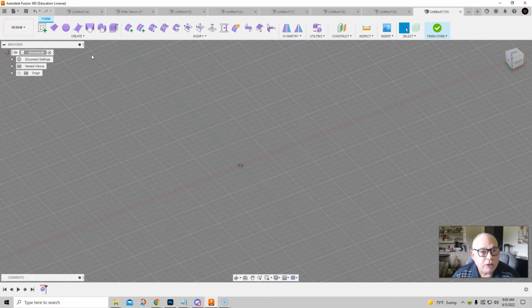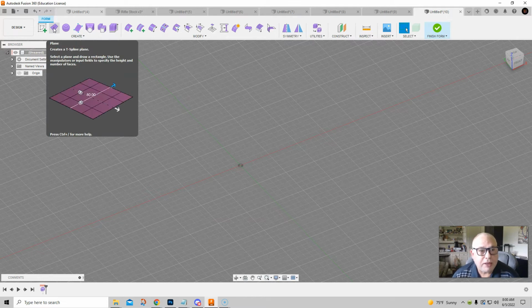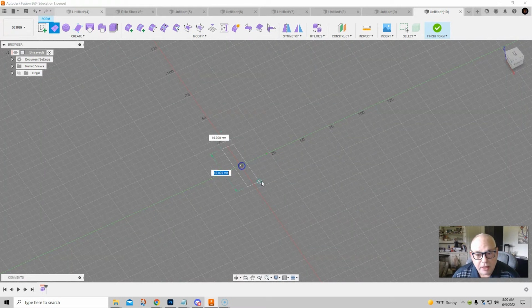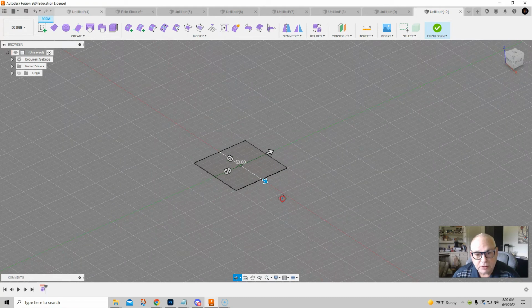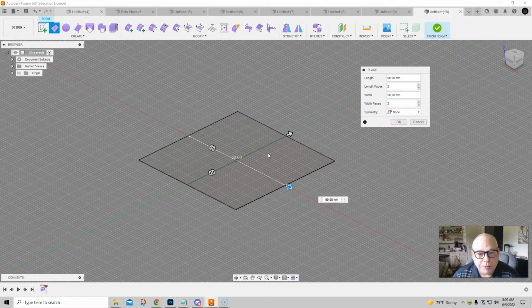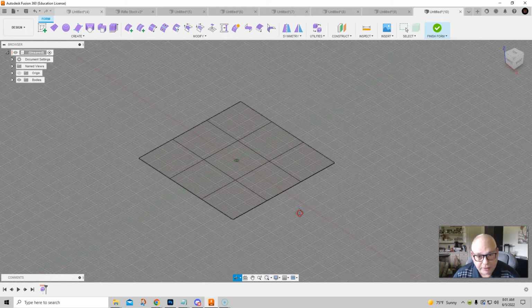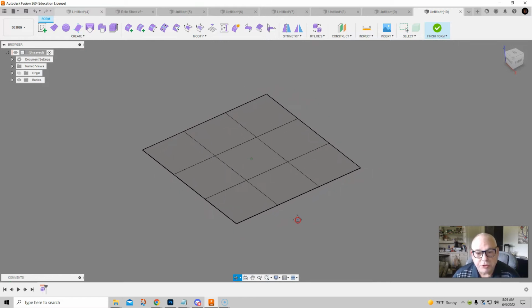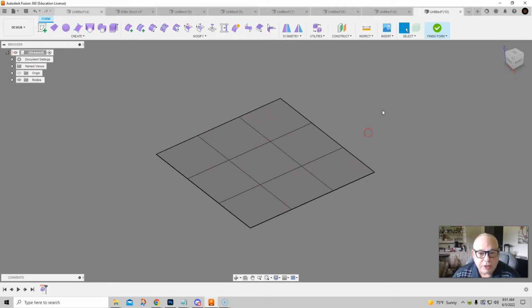We have different kinds of primitives, different ways to create things. We're going to start off with the typical way that you would do things in subdivision surfaces: we're going to create a plane on our ground, and we'll just make it like a box. When you're making these, tools will pop up. It defaults; I'm going to do 3 divisions by 3 divisions, and we'll set that in. I'm going to turn this layout grid off right now to make it easier for you to see. A typical thing you would be doing, as a little demonstration, is we want to extrude this up.